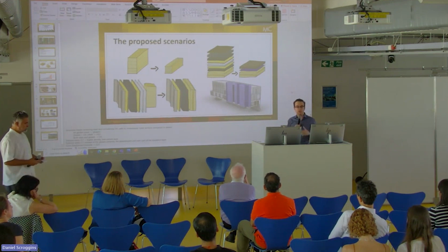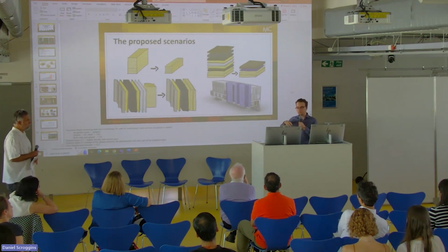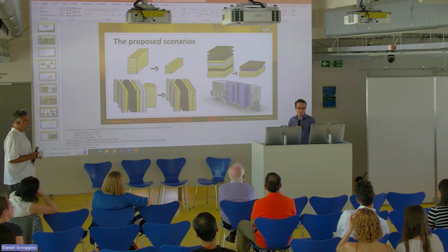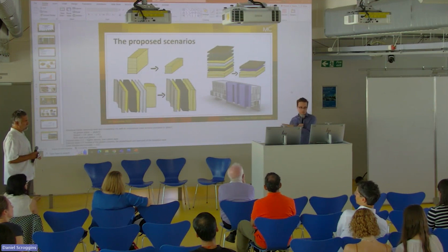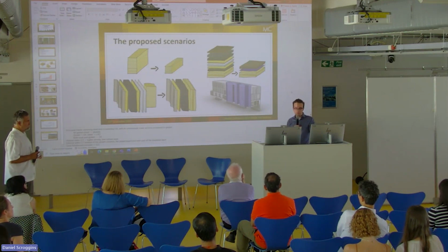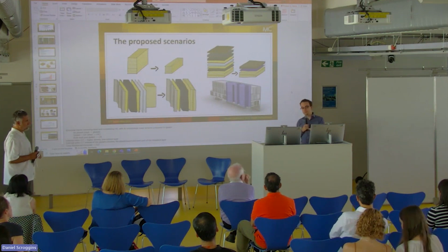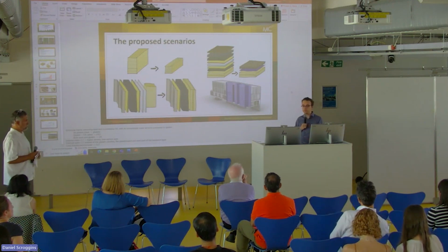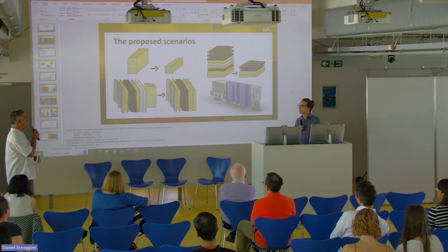Even though I considered the actual specifics of the CLT wall with its mass, I think these materials are just so lightweight compared to everything else. I also expected a bit of thermal mass to work in this scenario, but I didn't see it. The final operational energy numbers were very, very similar. So that's why I think it's important to couple timber elements, especially CLT for surfaces, with higher density materials. Okay, thank you very much, Agostino.